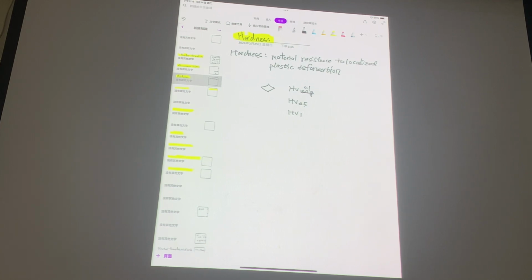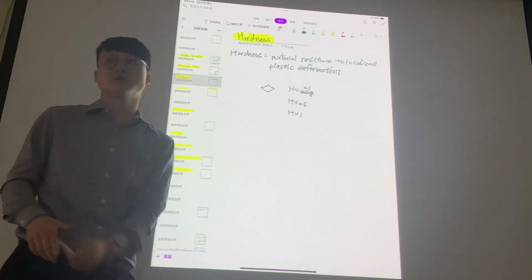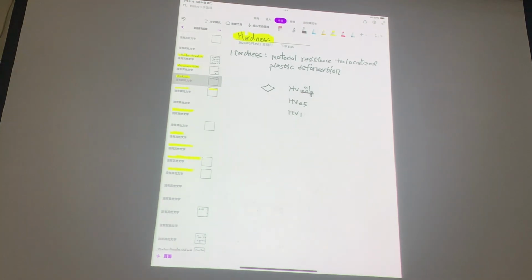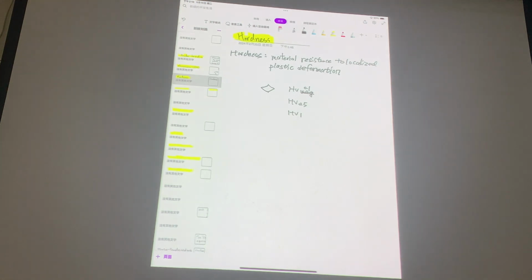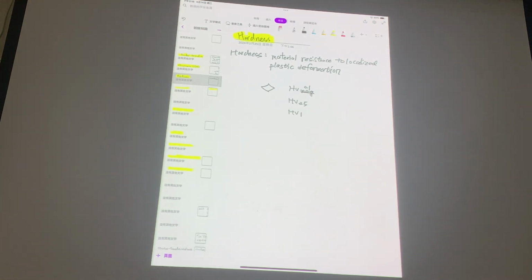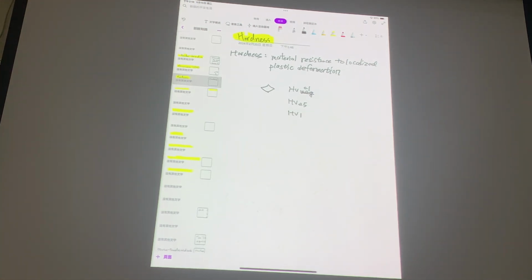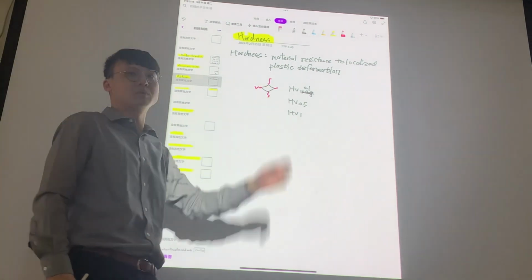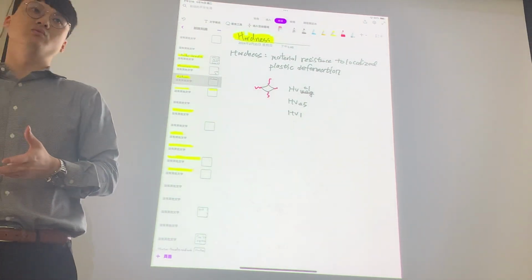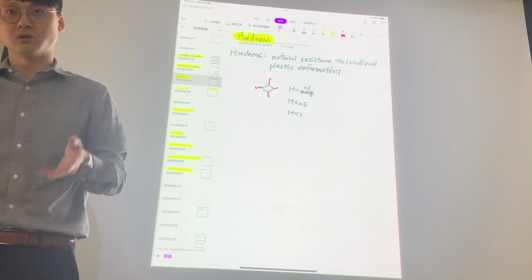And say you do this hardness test on the specimens, you might ask, hey professor, which of those should I use? One of the things or attributes you see from a specimen is that you see these kinds of things going on. So if you have potential cracks being propagated, I suggest you decrease your load.